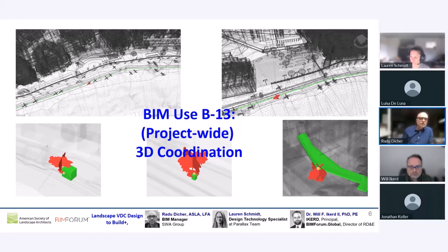There are certain specific aspects, like the one you mentioned, Will, the utilization of internal origin and project base point and survey point and other things like that, with their implications, which are the blind spots. Sometimes there isn't a knowledge of very slicey, if you want, aspects that are important to project-wide coordination.